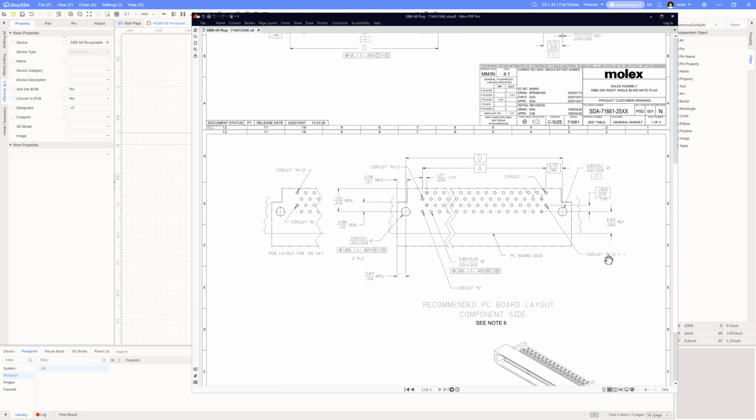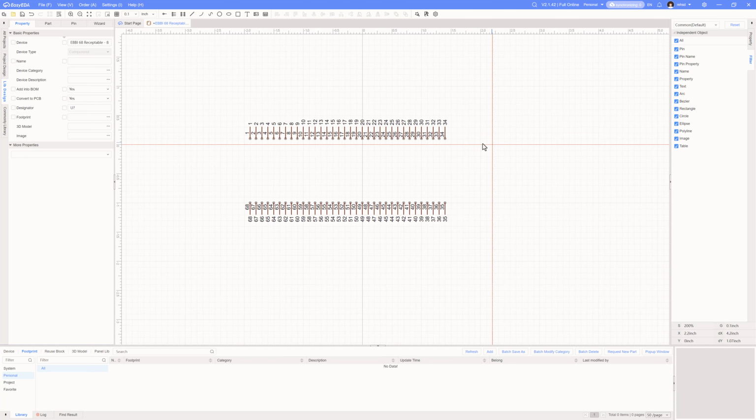So if it's a 68 pin, half of that is 34 plus 1 is 35. So this is pin 35 is how I read this. So pin 1, 2, 3, 4, and then I work my way up through the rest of them. So I might want to have a visual that shows 1 through 34 and then 35 on up. And that's maybe not how this is laid out.